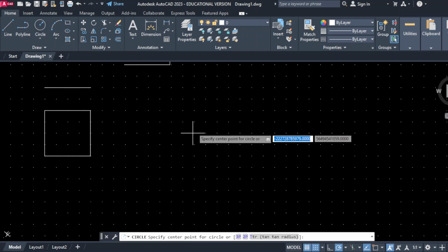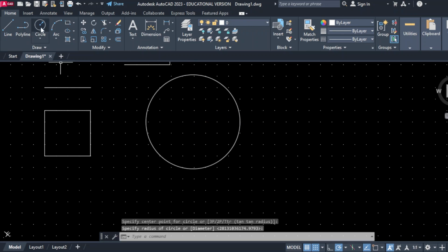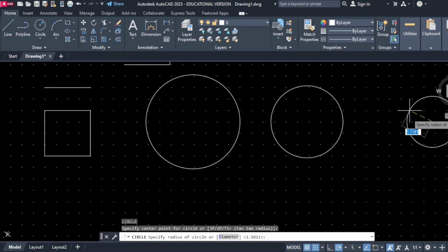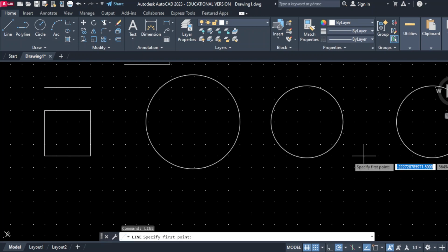Let us make a circle. Okay. And then again, if I have to make the circle, I have to again click it here. Correct. So if you wanted to do it quickly, you just press enter and the previous command, which was circle, will be invoked. Or using arrow key up, and you can see near the cursor the commands are coming. These are the previous commands. So if I wanted to make erase command, or let us say line, I can just go by the cursor, arrow up key and down key, and you can just invoke that command.